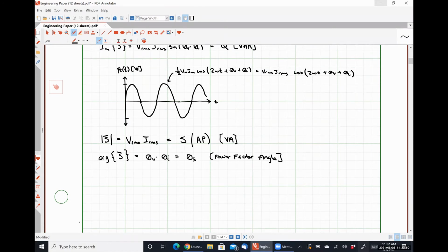What are the differences between wire and having a singular solid core? So a solid core of wire can carry more current before it melts and all that kind of good stuff. The biggest drawback is it's mechanically much more brittle, so you can't bend it nearly as easily. Running it through conduit is a lot harder.